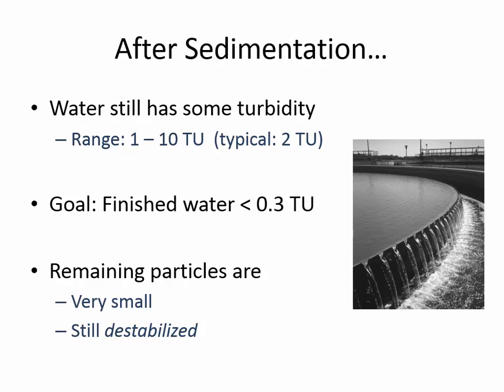Can anyone remind me why it's better to have groups of particles instead of just an individual particle? It's right, it settles faster. Why does it settle faster? Okay. Right. Remember from the formula, it's the diameter squared that sets the settling velocity.